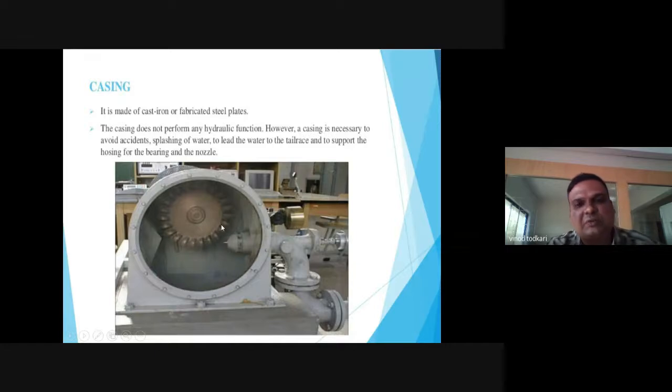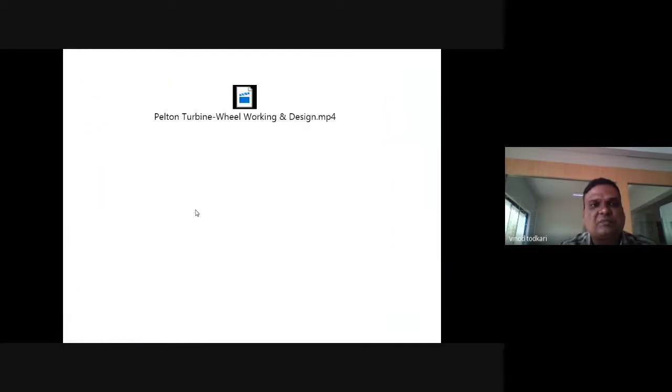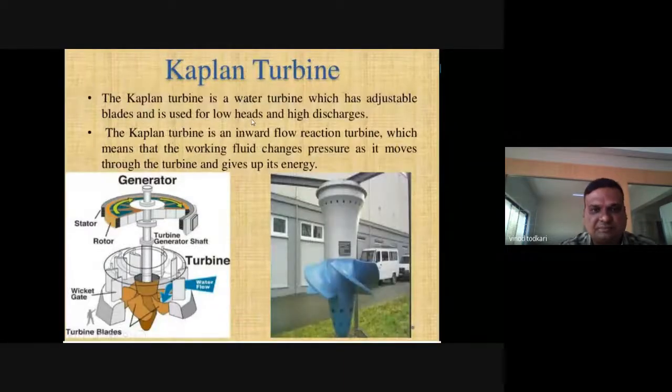Now see, in our laboratory, we have a fluid machinery laboratory, and in that laboratory we have this turbine. The name of this turbine is Pelton turbine. These are the buckets. From here the water jet is impinged, and due to the impact of the jet, this turbine rotates. So we convert the kinetic energy of water into mechanical energy. Yes, if you want, we'll see this animation.